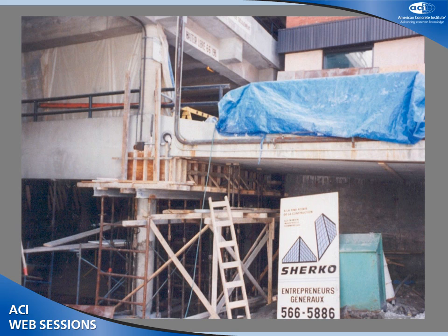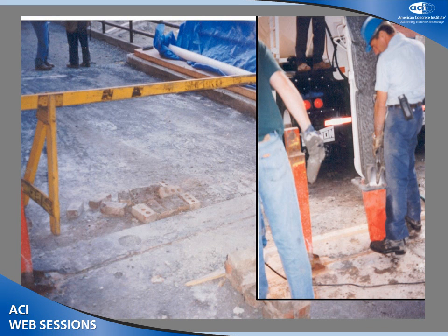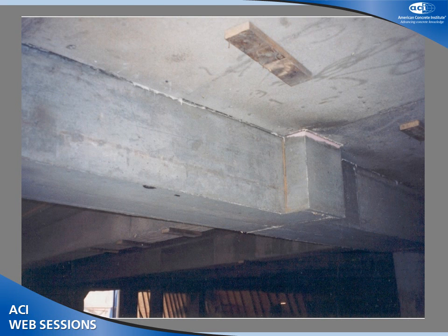This is typical detailing, and the placement was done on top, where the contractor cored 2 cores of 4 inches. This is about 6 meters. And then you have the bleed holes on the other side, so we always have to remember the bleed holes to let the air go out. The placement method was very easy. With a cone construction, cone inverted, concrete was cast in one place, and we had the bleed holes to observe and make sure that the concrete was coming out on the other side. To our great surprise, it worked very well, and it gave very nice surface quality.